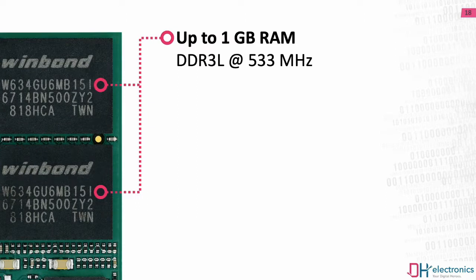When it comes to the memory, we're supporting the maximum of the memory which can be addressed by the STM32MP1, which is 1 GB of DDR3L memory. But when you look at this picture, you might wonder, why did we choose to go for the 2-chip design, right? I mean, this board is already super crowded, and we just figured out that we didn't include any eMMC or any other bigger flash storage directly onto this board. So why did we then choose to go for the 2 DDR3 chips instead of just a single one?